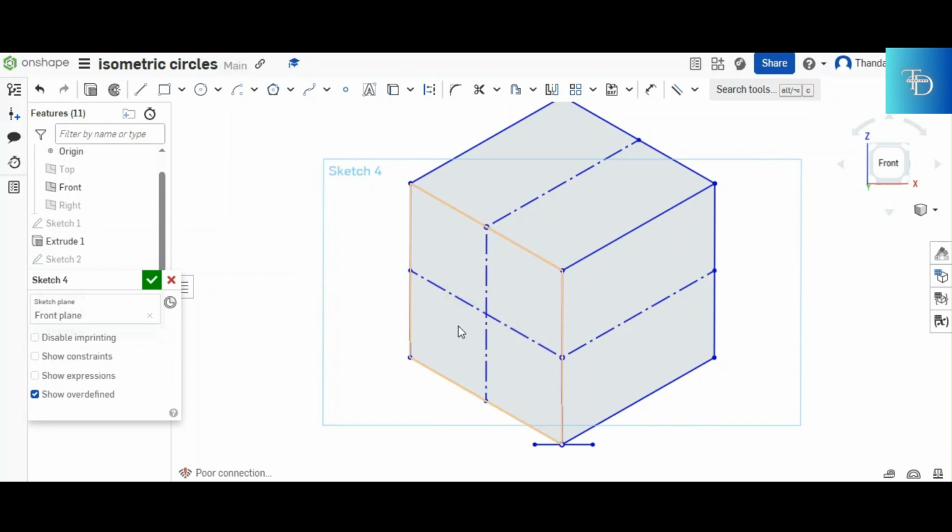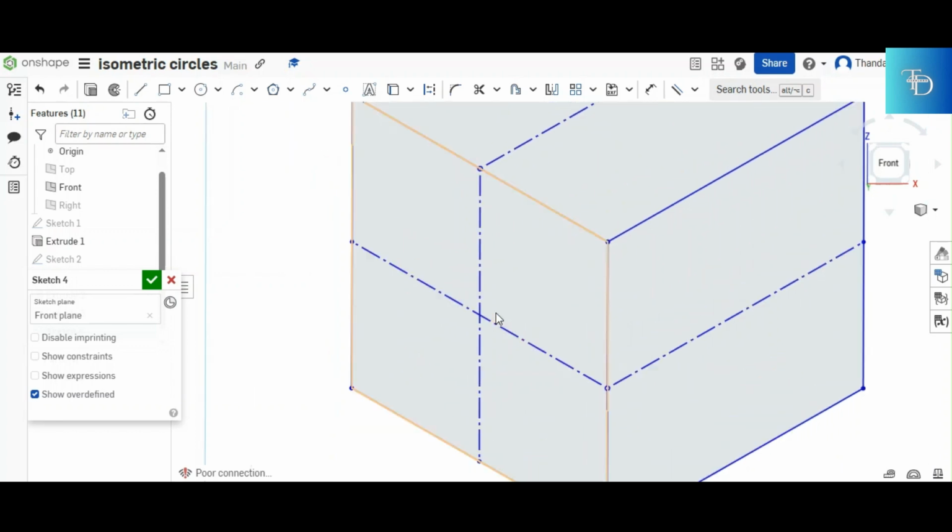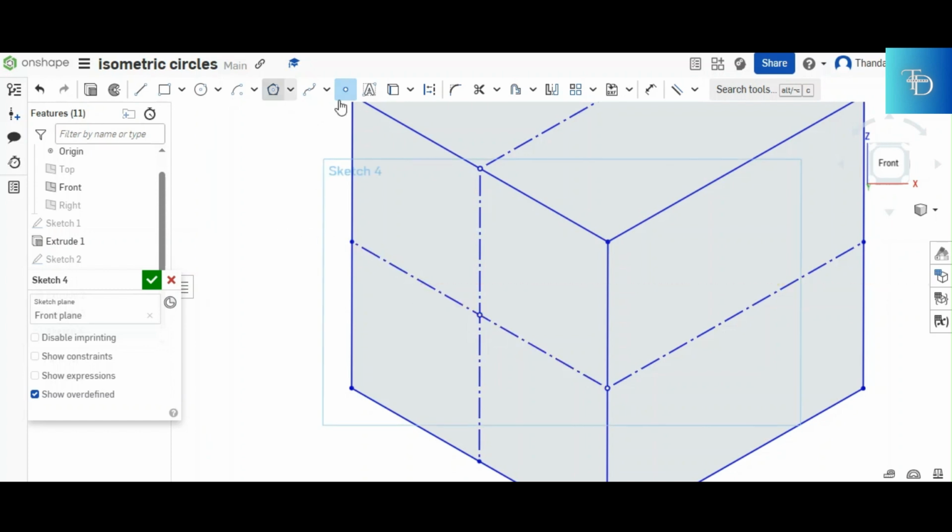So now you're done with your center lines. The next thing that you do, you take your compass, you open it up to 25, because remember the diameter of the circle is 50. You take your compass, you open it up to 25 millimeters, and then you use that center point right there to mark 25 millimeters there, 25 millimeters there, 25 millimeters there, and another 25 millimeters there.